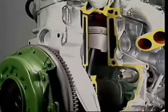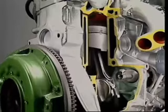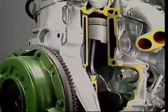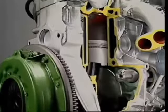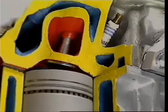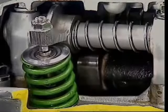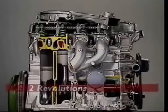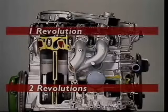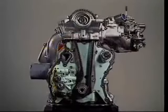In one cycle of a four-stroke engine, from intake through compression, ignition, power and exhaust, how many times does the crankshaft turn? Twice. It makes 2 revolutions. During that time, what happens to the valves? They open and close once. So the cams must turn through just 1 revolution, as does the camshaft. In each cycle, the crankshaft turns twice and the camshaft only once. So the camshaft must turn at half the speed of the crankshaft.